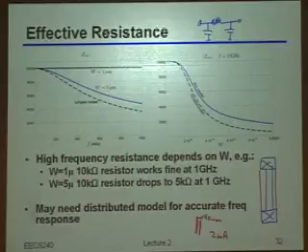Okay, so sometimes indeed what you have to do is use a wider resistance, wider in the layout, simply because of the current you're trying to handle. This is a general thing to keep in mind: anytime you deal with large currents, that tends to mean you need larger physical elements, which tend to have larger capacitances associated with them, which tends to mean you need more currents,